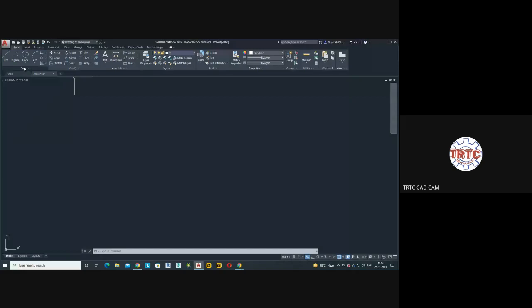Okay, so what I was saying is that I can take the line. First thing, you can enter the coordinates with a comma. It is asking to specify the first point of the line. So you can press 0, comma, and 0. Once I hit enter, it will take the first point as 0,0, exactly the same as my origin. This is called UCS, user coordinate system.